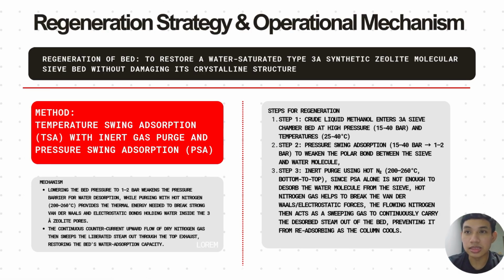I'll be presenting the regeneration strategy and operational mechanism. So the meaning of regeneration of the bed basically means we restore the water-saturated zeolite 3A sieve without damaging its crystalline structure. The method that we use is temperature swing adsorption combined with inert gas purge and pressure swing adsorption.